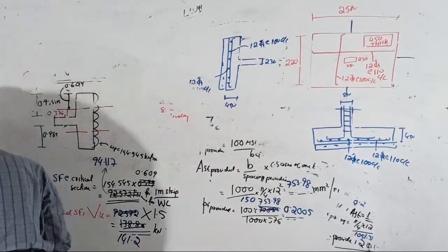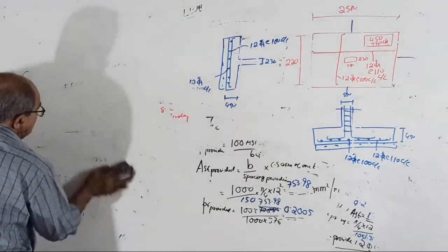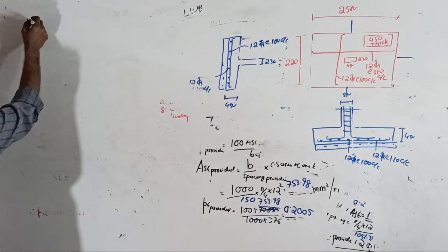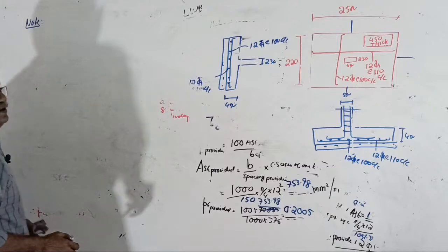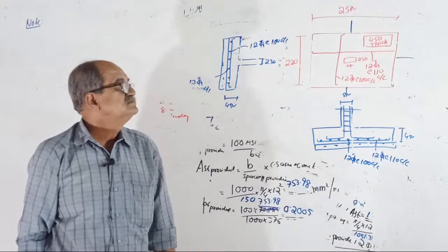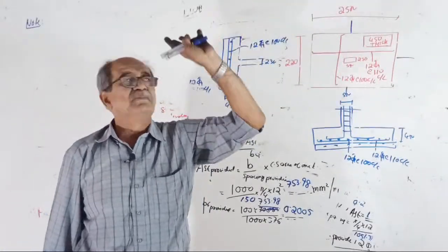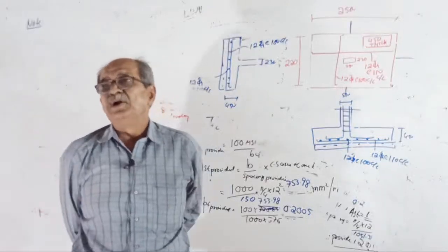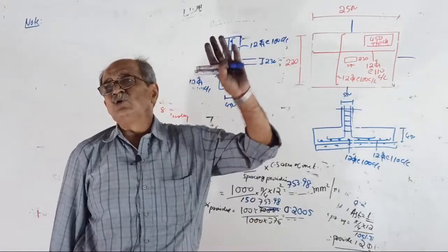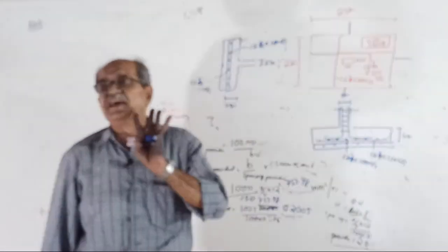Okay. Now, I will go for the important part now. That is what? See, make a note here. Make a note. Design, when you design by software, that is SAFE, ETABS and SAFE, you are importing the load, etc. from the ETABS. Therefore, you don't have to apply the load. One. Second, all load combinations there will come here also. ETABS will design for critical case.